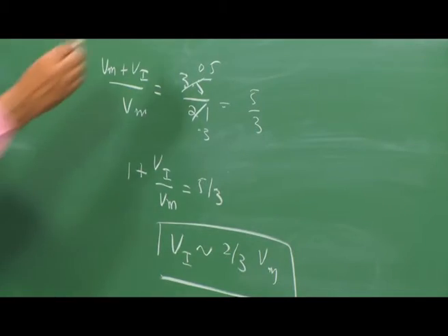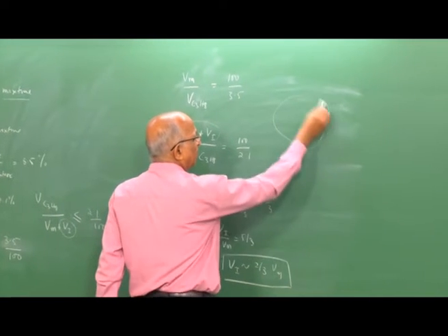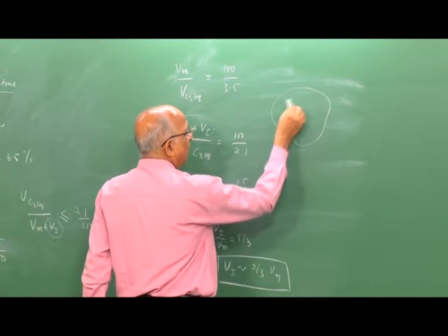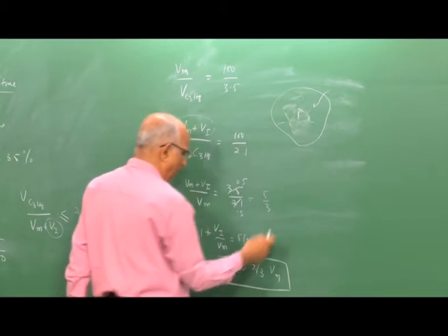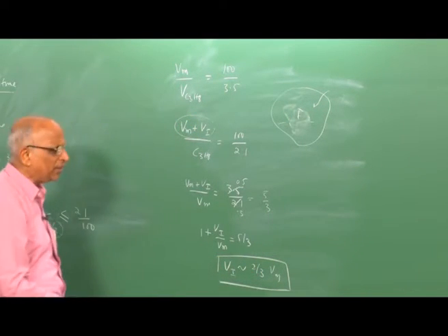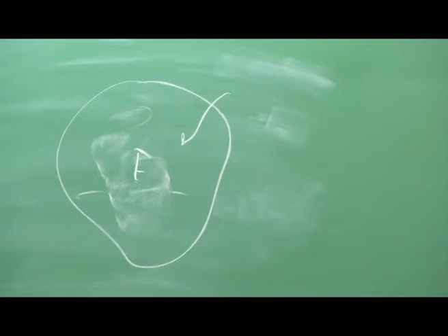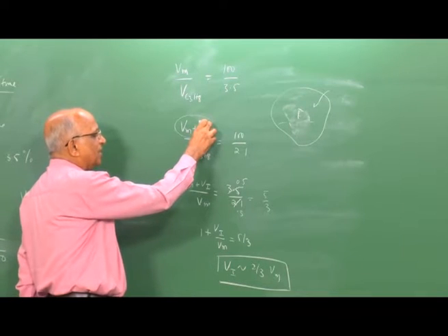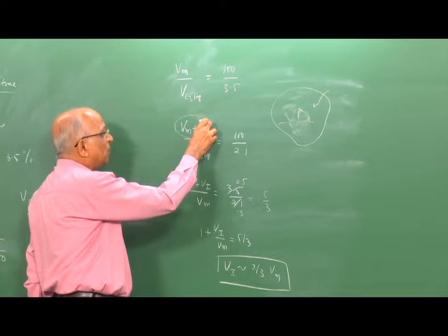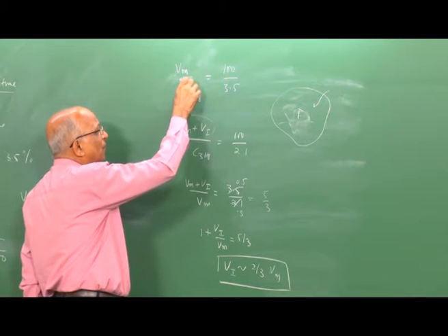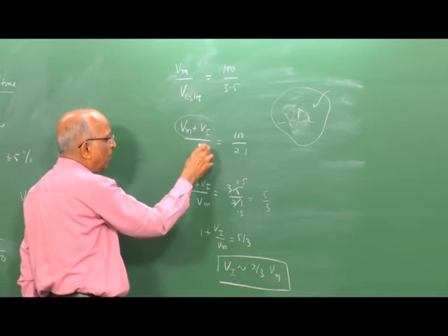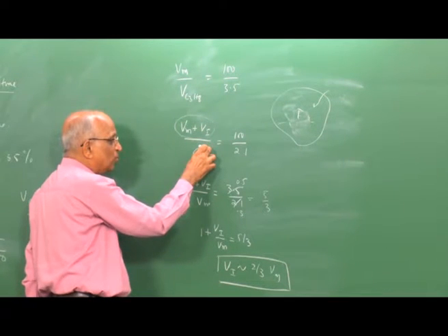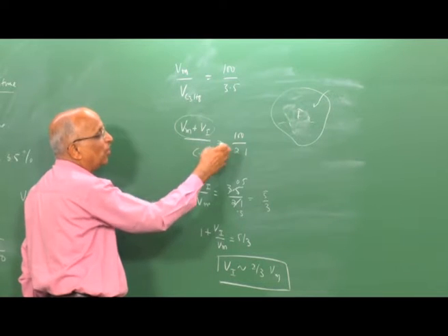Therefore, if I have a mixture, let us say in a fuel tank or some place, wherein I have gases which are flammable, how much of the inert gases do I need? This becomes a simple way of reckoning. But we must also remember that if I have an inert gas like nitrogen, whose properties are similar to the fuel and air over here, well, the effectiveness is there, but if I can add gases whose specific heat is higher, it is going to be more effective.